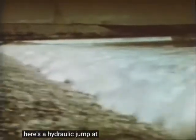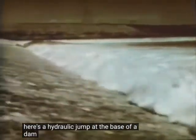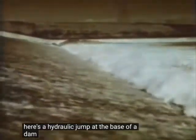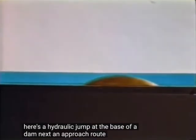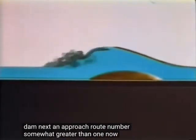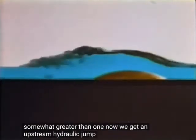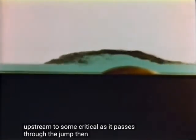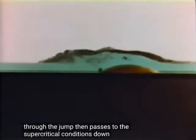Here's a hydraulic jump at the base of a dam. Next, an approach Froude number somewhat greater than 1. Now we get an upstream hydraulic jump. The fluid goes from supercritical far upstream to subcritical as it passes through the jump, then passes to supercritical conditions downstream as it passes over the obstacle crest.